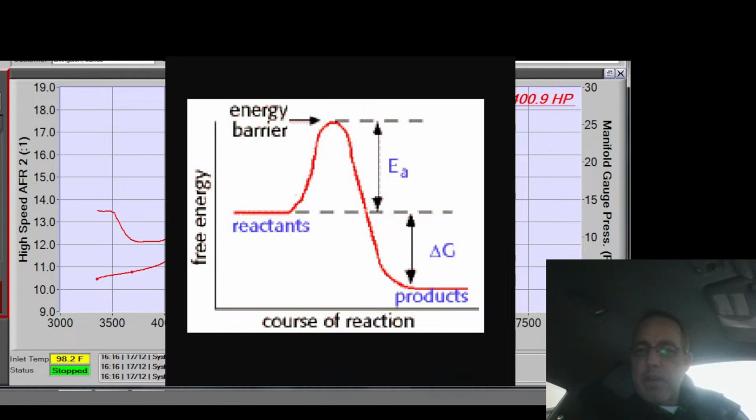The same paper I read also talked about using EGR to help the burn. Yeah, so EGR to help the burn is a lot about warming those reactants. If I warm those reactants, raise their energy state, and distribute them better in the cylinder, then I help them ignite.